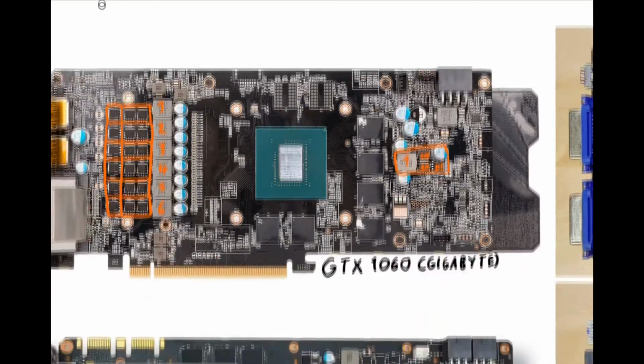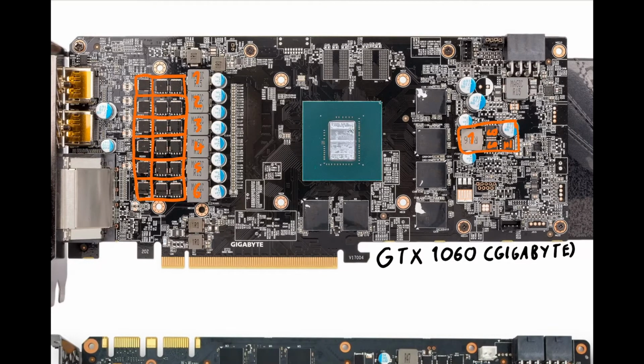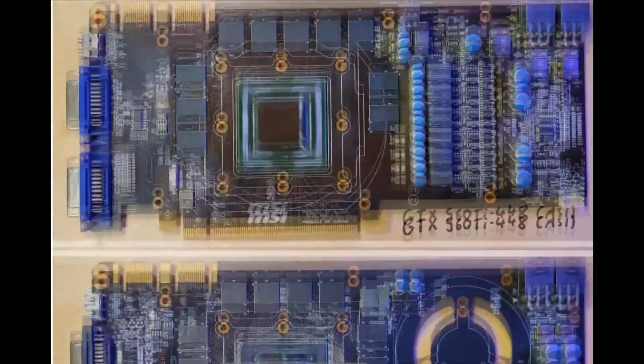When overclocking, VCore is always going to be the most interesting VRM, because yes, you can overclock memory, but you can't really give it more voltage. On some AMD cards you can give it more voltage, but even then the VMem VRM is not that interesting, because most of the time VMem is using way too powerful MOSFETs for what it actually needs. So you will basically never max out that VRM or even get close to it. Whereas on VCore, cheaper cards can max out their VRMs a lot.